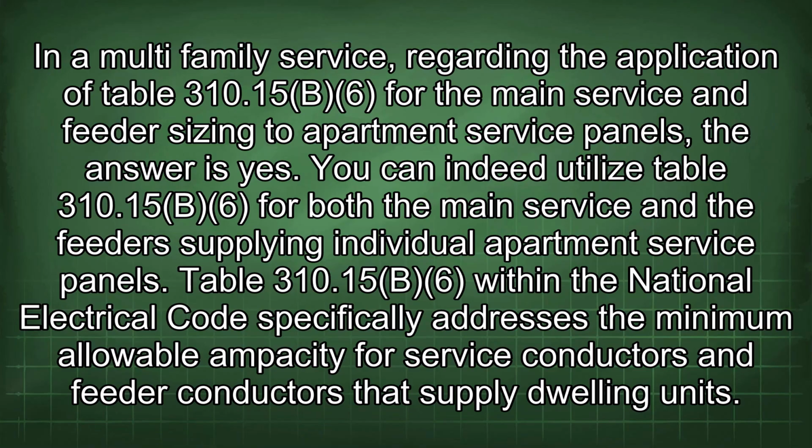Regarding a multifamily service and the application of Table 310.15(B)(6) for the main service and feeder sizing to apartment service panels, the answer is yes. You can indeed utilize Table 310.15(B)(6) for both the main service and the feeders supplying individual apartment service panels.